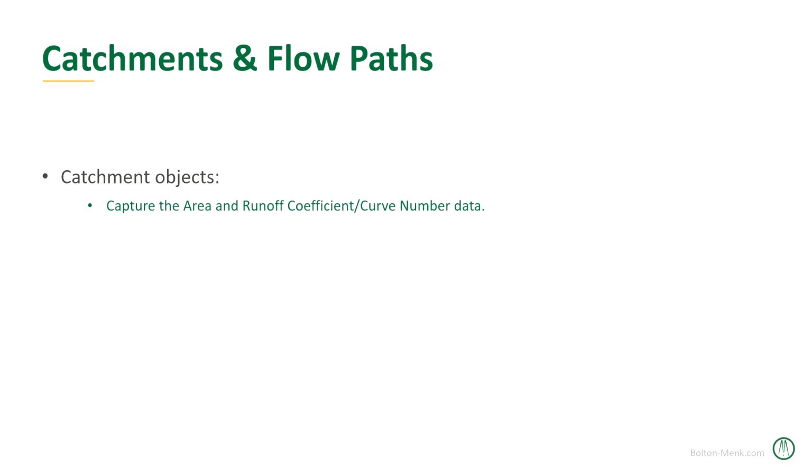That's going to be a really nice summary tool that we can put together on a drainage exhibit or pass along to our modeling software. They are also dynamic Civil 3D objects. So as your model changes, maybe your proposed conditions get some different elevations in them, and you got to rearrange stuff, it might be a touch unfortunate to have to click and drag those different vertices around, but you do have the option.